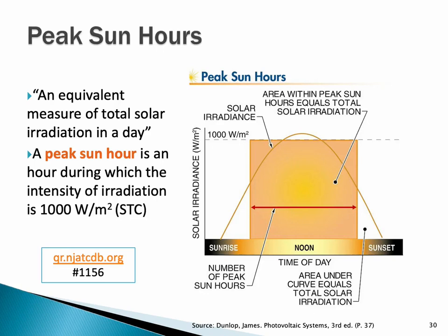And so if we add that all up together, we get this cumulative peak sun hours, or we have an equivalent to, say, 4 sun hours per day, or 4,000 watt hours per day, 4 kilowatt hours per day, cumulative.